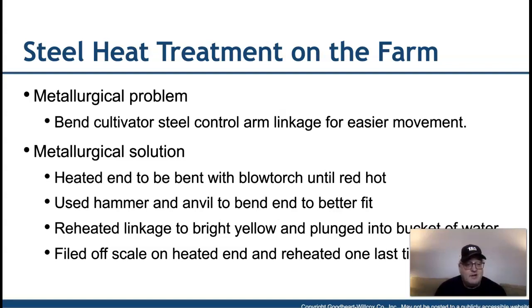And of course, the more experience you get, depending on what type of steel you're using when you apply the torch, you learn some of the different colors of that steel, whether it's an orange or a red or a yellow, and you start to gauge the temperature of the steel based on the color when it's glowing hot. You use that experience to tell the relationship between the color of the metal and the temperature it is at, so that you know it's ready to bend and process.